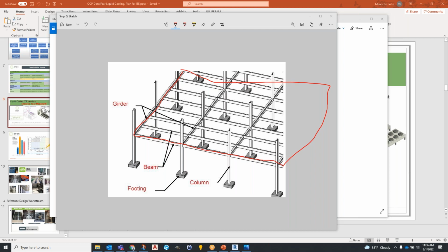So, right now the preliminary spreadsheet that I've put together is basically looking at width, depth, and height: what the actual equipment footprint is in those three dimensions, and what the clearances are on each side of that. With the width, you've got your left side clearance and right side clearance, because it's not necessarily the same for every solution. Depth, you've got the rear clearance and front clearance. Height, you've got any overhead clearance and any underfloor clearance, right? For folks that are connecting in from the bottom. And then I've got an empty weight and a typical wet weight.